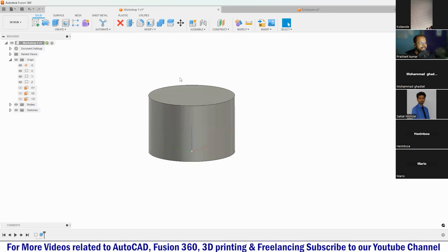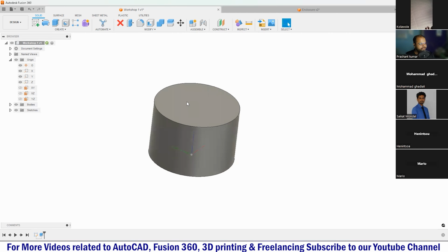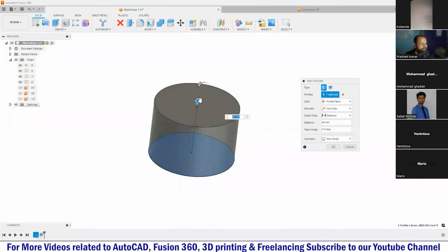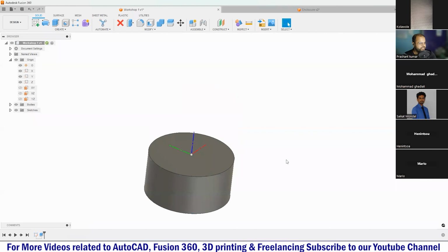For example, in this model I had created towards upward, right? I had extruded towards upward. So you can say that we are into the positive direction of the axis. Now, if I make a right click on the operation that I had performed and click on edit feature, and now if I drag it towards the bottom, I can do that. That's completely fine. I just had to put the minus sign in front of it, minus 30, like that.